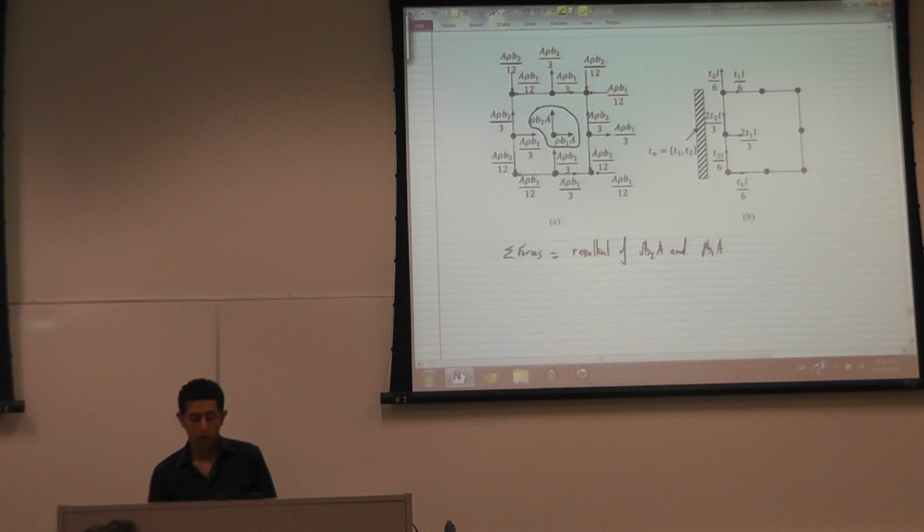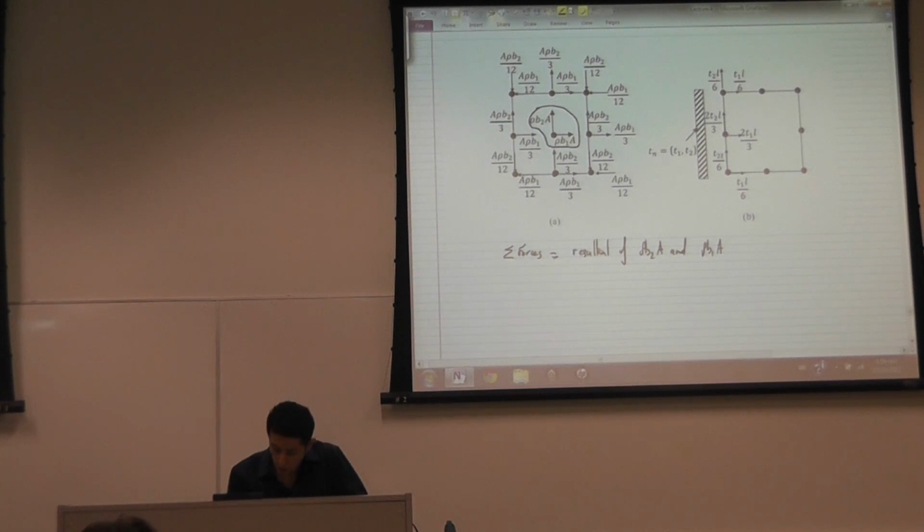So the sum of forces is okay, but for some reason, and we'll talk about it right now, the corresponding forces that would be equivalent to applying rho B1A to the whole object are, if I call this F, 1/3, 1/3, 1/3, and 1/3. So you have an extra third, and this extra third is input as a negative, or in the opposite direction, on the vertices.